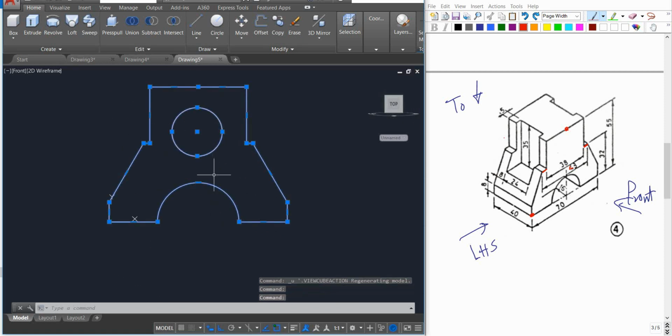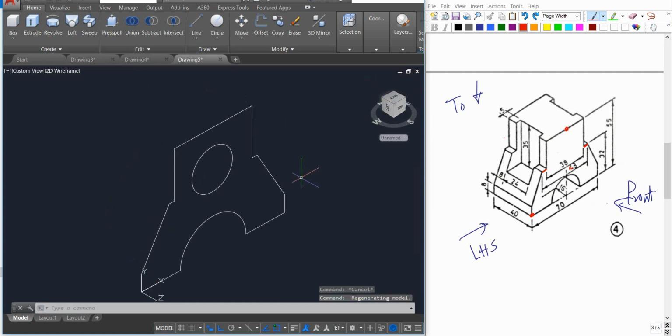but this second loop, this circle, should represent a hole inside the shape? You can use Press Pull directly and the hole will be formed automatically, without spending time with the subtract. So with Press Pull, your objective is just to click inside between the two. Don't select either of these two loops. Click on the area between them.